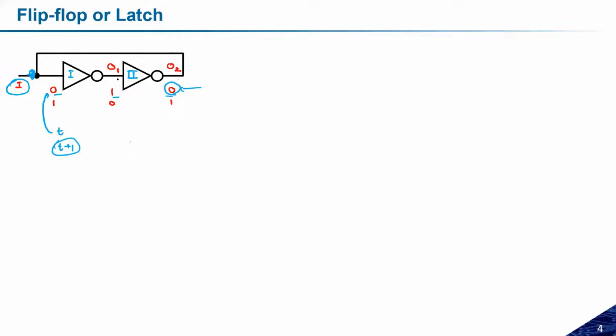Now if you see, these outputs are blocked, they are latched, they are not changing their states. So this kind of logic we can call a latch circuit. At each instant of time, you will get the same outputs. The output is not going to change if I am not changing the input pulse. For one time, let us say I have triggered it with 0 to 1, and during this time period the circuit is triggered, and after I remove this input, the logic will be latched at both the outputs O1 and O2. If they are latched, we can call them a memory element.